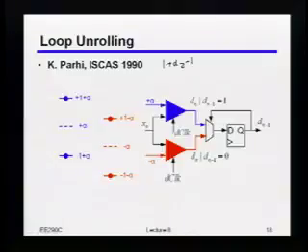Okay? So if that's the value of the coefficient, then the way you'd build this is you'd say, well, let me just take 2 comparators. One comparator, its threshold, I'll shift by plus alpha, which means that I'm assuming that the previous bit was a 1. The other comparator, I'll shift by minus alpha. Plus alpha meaning I assume the previous bit was indeed a 1. And minus alpha, I'm assuming the previous bit was a 0, or equivalently a minus 1, right? So by shifting the threshold, I'm creating that subtraction. But then after the fact, once I know what the correct previous bit actually was, I go back and select what the new current correct decision actually is.